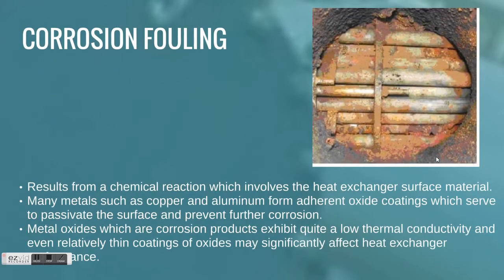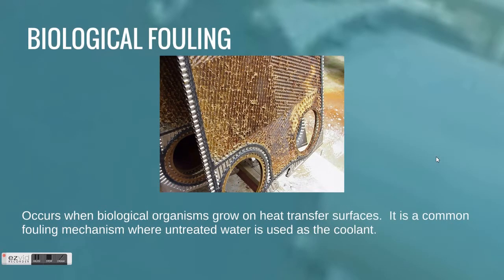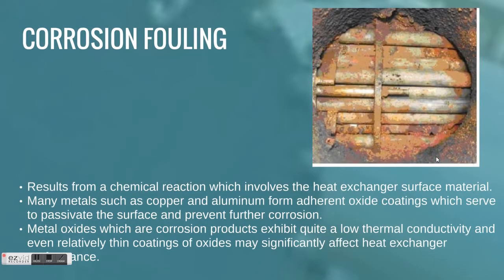Biological fouling. Biological fouling is generally caused by the overgrowth of different organisms within the fluid. This is then deposited onto the surface area of the heat exchanger. The type of biological fouling is typically influenced by the material choices used. One notable material that can influence the layers of fouling is non-ferrous brasses, which are poisonous to some organisms.